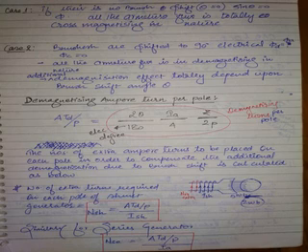Ampere turn means if you write there are Z by 2 number of turns in the armature, you have to write what is the current flowing in these turns only, not somewhere outside. Am I clear? Where is this Z or Z by 2? Inside. These are Z or Z by 2 conductors inside. So if you write ampere turns, that product should belong to inside the armature, not outside current into inside turns. So what is the current flowing in Z by 2 turns? It is IA by A.